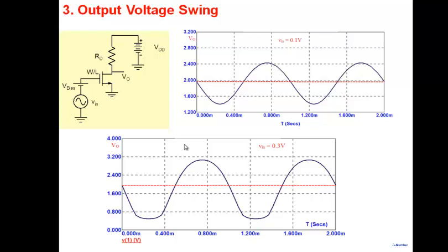And if gain becomes small, what does it mean? That V0 becomes small, because Vin is the same, so V0 becomes small there. That's why you begin to see some saturation occurring there. Now, saturation of the voltage waveform, not saturation of the transistor, okay? Please keep these terminologies in mind. So the transistor is entering into linear region.